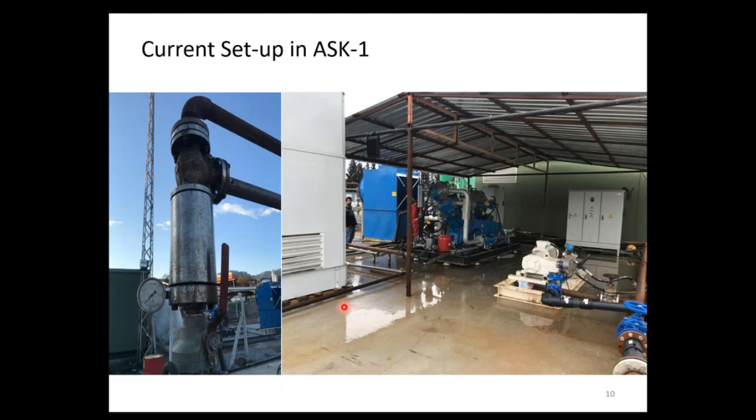Without filtrating or without any purification, even with some little amount of vapor, we compress all of them together. We don't need to do any filtration or purification for the gas. We just collect it, cool it down, and pump it as it is. For that, the compressor's internal surface should all be stainless, resistant to highly corrosive gas or highly corrosive fluid.